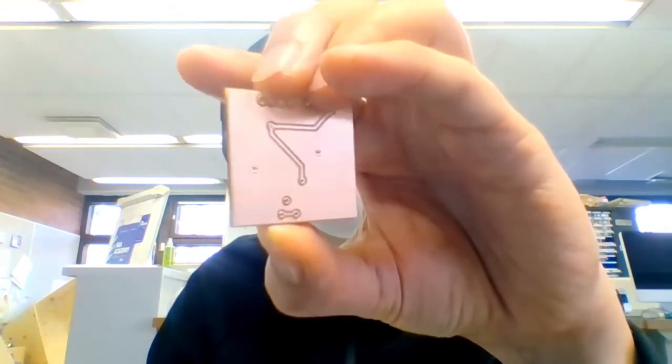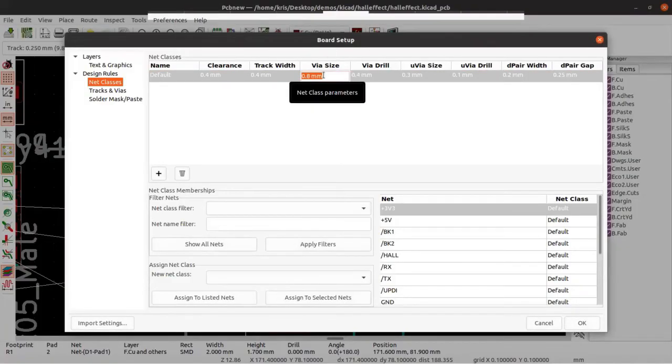In order to make these in KiCad, you need to understand the concept of vias. And it starts with defining the via size. The drill that we're going to use for the smaller vias is going to be 0.8. The via size should be bigger than the drill because it needs a little copper ring around the hole to be able to connect to the actual copper layer. I usually make it 2 times bigger. So if the hole is 0.8, then 1.6 millimeters should be enough copper.